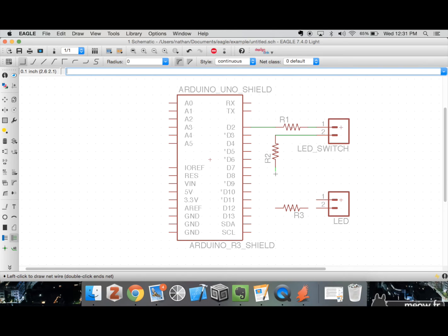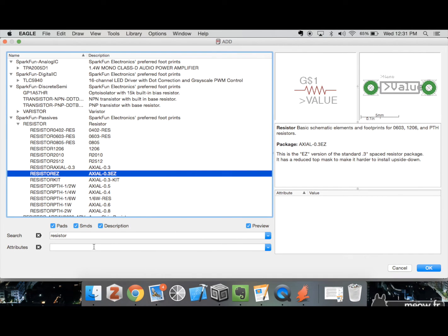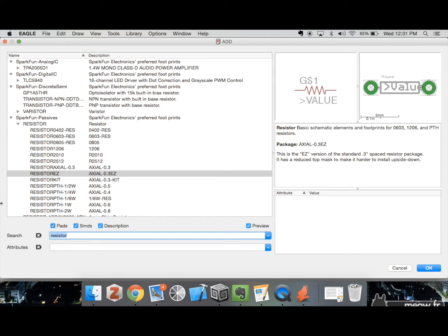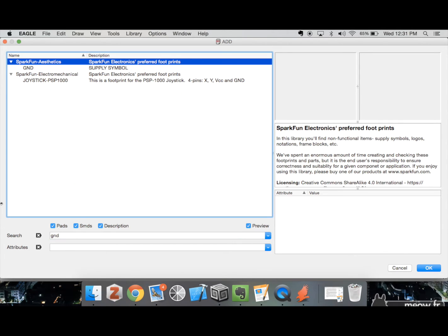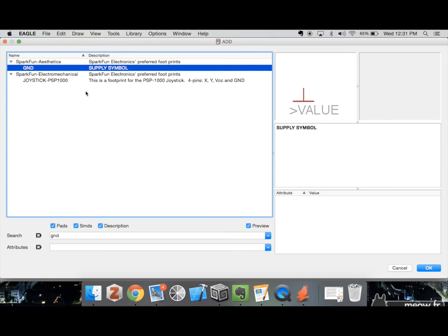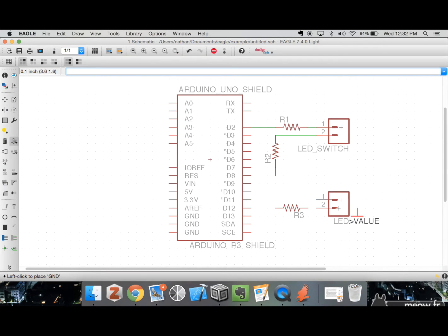And then I'm going to give myself a little bit of a lead to attach to the ground. And actually, in order to add the ground, I'm going to type in add here and press enter. It's going to open up our component searching dialog here, and I'm going to type in GND, which is short for ground. I'm going to grab this ground here, so that's a ground symbol. The other one will have the 3 lines getting smaller underneath each other. They both mean the same thing. I'm going to grab that, and I'm going to click it on the bottom here.